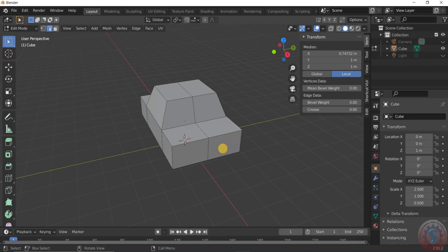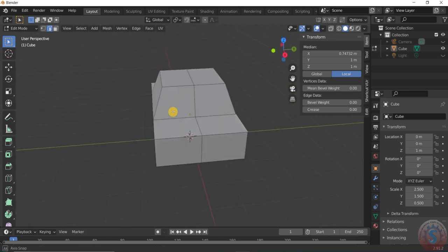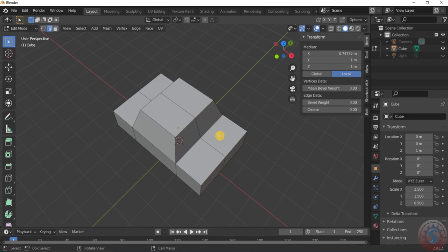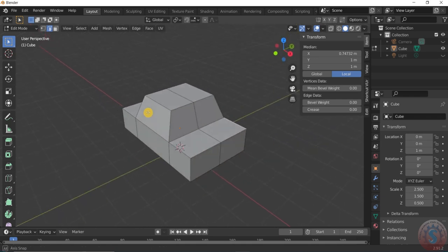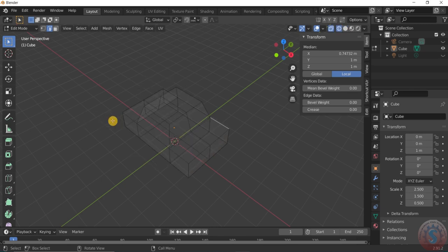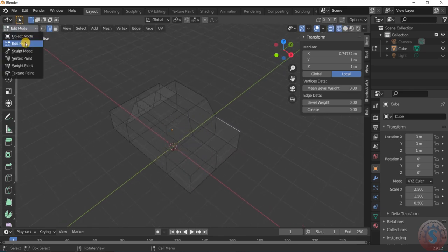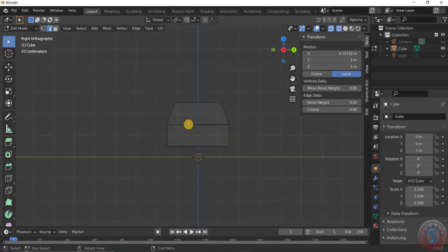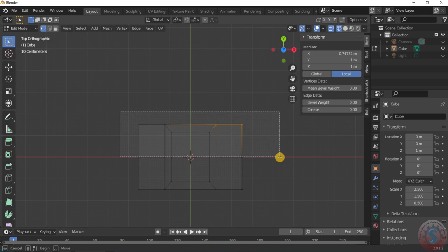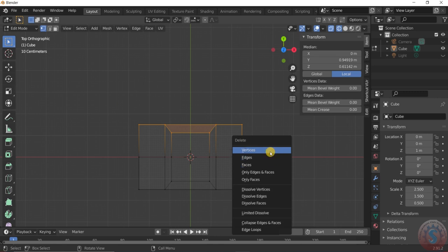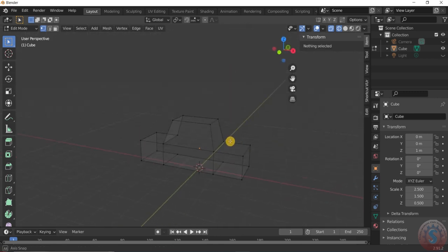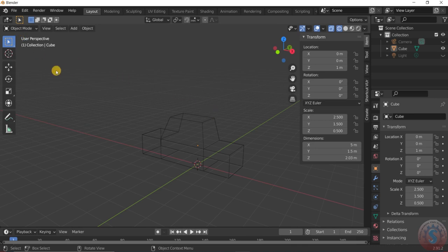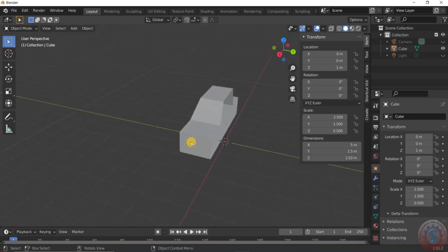Another view is made by using the mirror modifier. I will create this, delete this other part and keep one part as constant. By using the wireframe, you can delete it easily in the edit mode. Go to Z and the wireframe. By selecting the vertices, you can observe them like this. When clicking on the vertices, select all of the vertices on the other side and click the X or delete key and give the vertices. Then half of the part is deleted, and go into the object mode and select the solid. Half of the part is deleted.